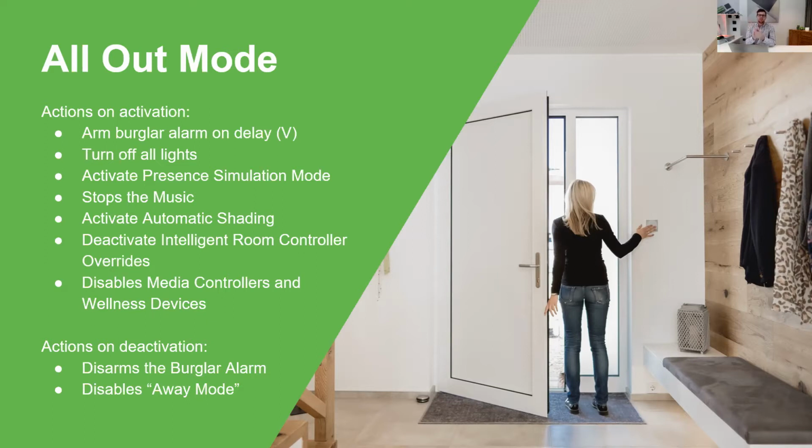And so I've mentioned all-out mode before. Now, our recommendation, part of the Loxone standard, is that any switch that leads to the outside world, as in that picture there, our hallway switch, we should be able to triple tap that switch and it should turn the whole house off. Now, I've already demonstrated that to you with the burglar alarm, that when we triple click this switch here, the burglar alarm arms. Why don't we bring other things into that as well?